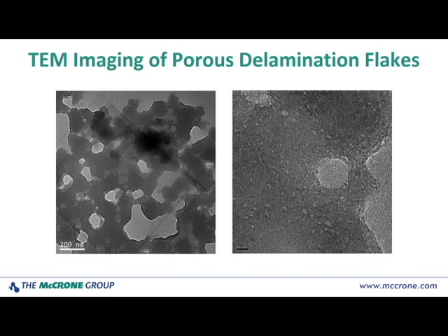You can see that a lot of these holes are actually extremely small. And again, seeing this can be an earlier indication possibly that you have glass delamination going on. You have the opportunity and the capability in the TEM to see much smaller features such as pitting and porosity that you might not recognize in the SEM.